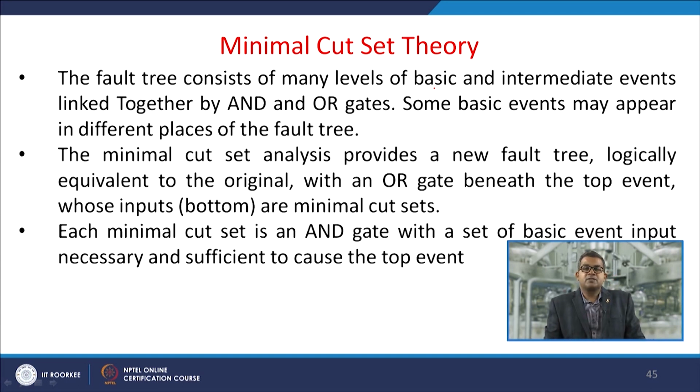Now, the minimal cut set theory says that the fault tree consists of many levels of basic and intermediate events linked together by AND or OR gates. Some basic events may appear in different places of the fault tree. The minimal cut set analysis provides a new fault tree logically equivalent to the original, with an OR gate beneath the top event whose inputs, sometimes at the bottom, are minimal cut sets. Now, each minimal cut set is an AND gate with a set of basic event inputs necessary and sufficient to cause the top event.